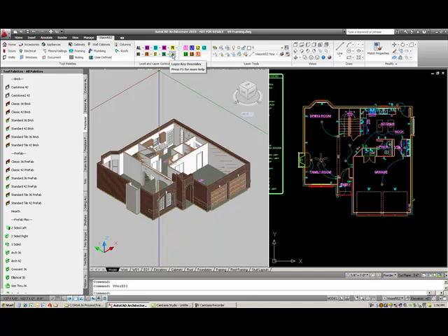This will only be used if we want to put something on an optional layer, like a different front elevation that we might not want to see in our typical working drawing, but we might want to see in a partial. And you'll also notice there's a down arrow here on this tab. We have a separate set of controls for the layouts. If I select this pin here, it'll lock that in so I can get at those tools. But when we're in our layouts, we'll have a separate set of controls that control our viewports.